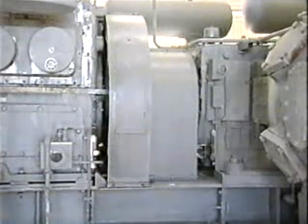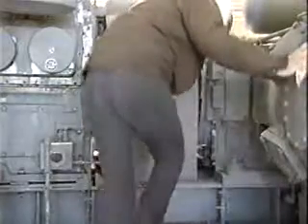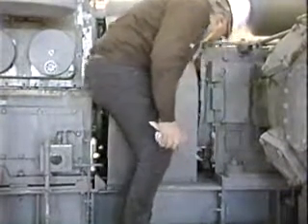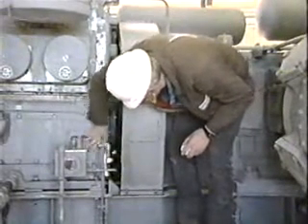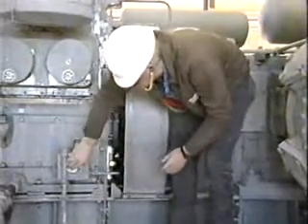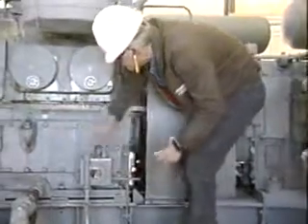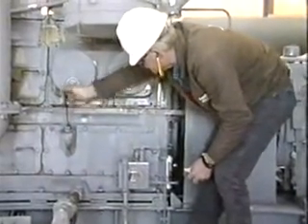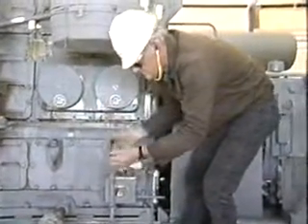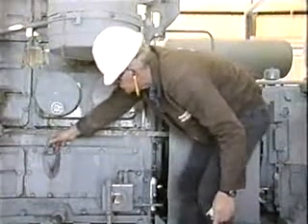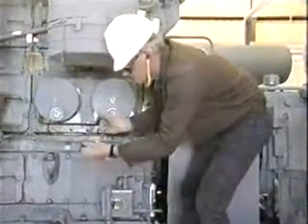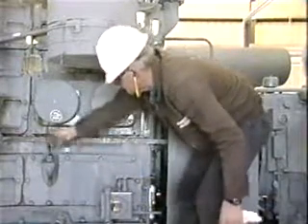It is extremely important that the person responsible for operation consistently check the oil level on the compressor, either by looking at the sight glass or the dipstick if one exists. Then be sure to add oil as needed. On the prime mover, the lubricant continually circulates through the lubrication system and will eventually deteriorate. So the lube oil must be checked and analyzed at regular intervals and changed when needed. This is similar in nature to changing the oil in your car at regular intervals.